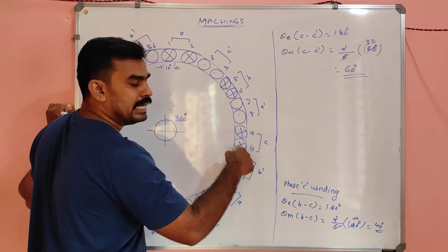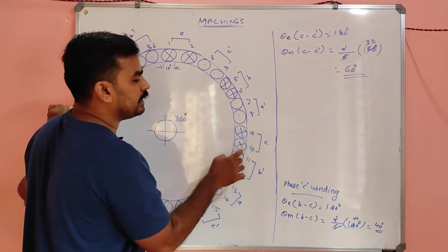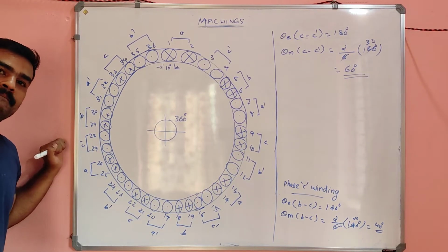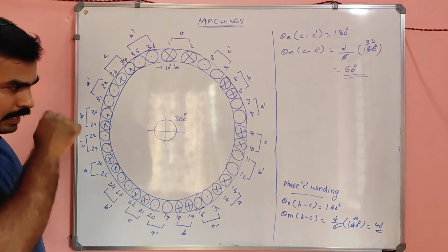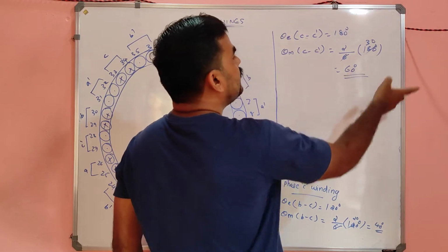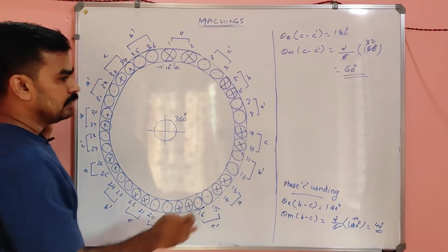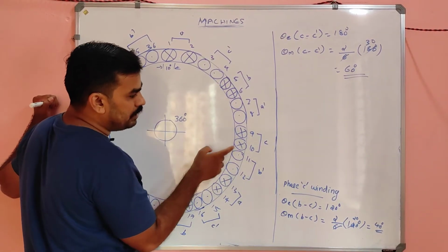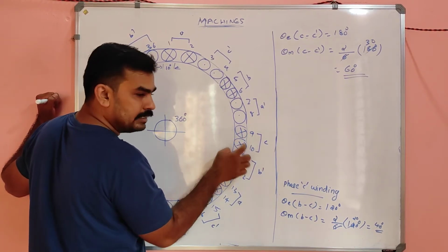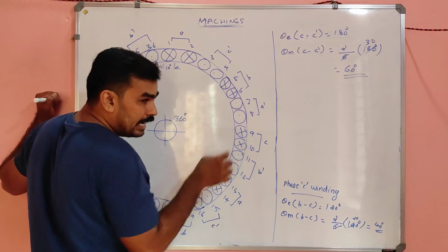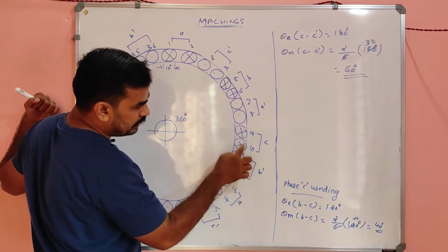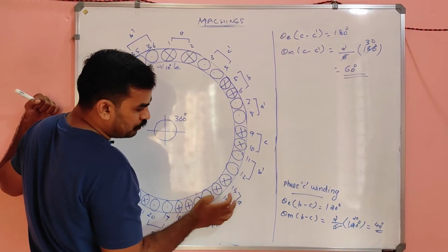So this will be the starting end of C. That means in coil number 10 is the starting of C. Okay, and the C dash will be after 60 degrees from C. That means this is C now. So after 60 degrees, C contains these and these. Okay, so in between, the angle measured, the C dash will be 60 degrees away, means 10, 20, 30, 40, 50,